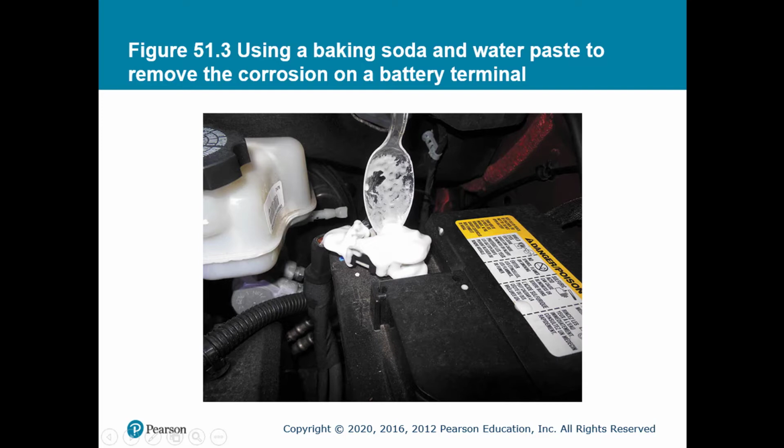So if I have a terminal that's full of corrosion, I'll remove the terminal and I'll actually put the terminal inside a cup of water and baking soda solution. So that way it can work its way into the actual terminal and get to those hard to reach areas. If you have a significant amount of corrosion on this terminal, it might be worth replacing it completely. And by that, it might not be just the terminal, it might be the actual cable itself.